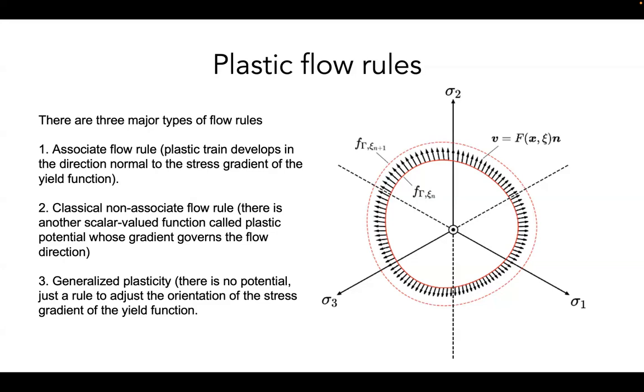There are multiple ways to derive the plastic flow rule. The most popular and simplest one is to use the associative flow rule. What it means is like what we talked about: I simply use the yield surface also as a potential to manifest the different modes of the stress. Notice that, in my opinion, it's only the direction of the plastic flow that matters.